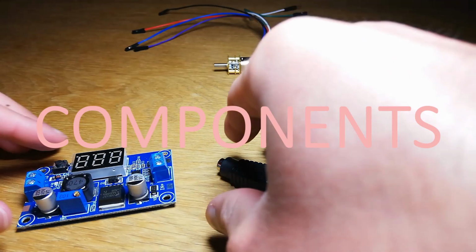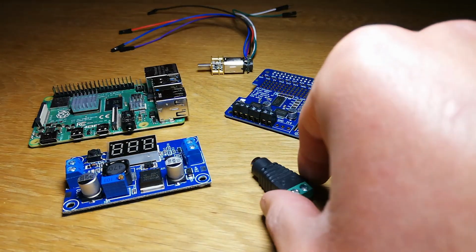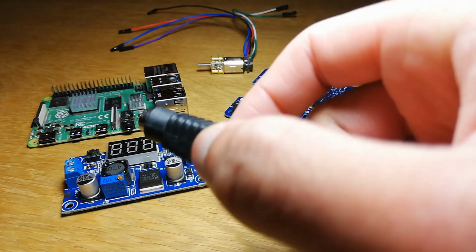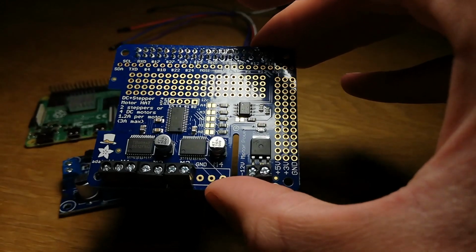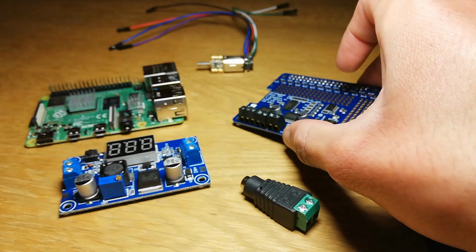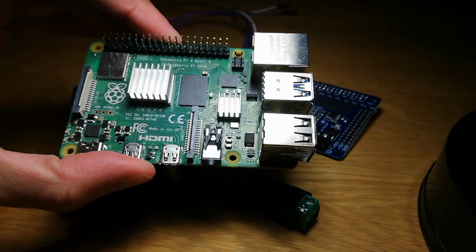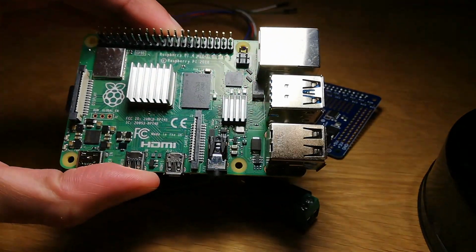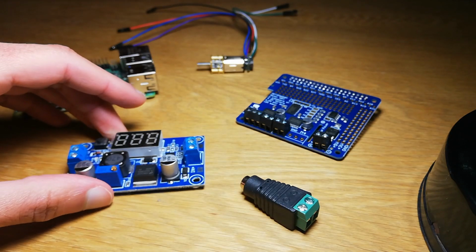For our power input, we're using a female DC jack barrel. This will be connected to a laptop charger. To control the motor, we're using Adafruit's motor controller hat. This generates the PWM signals needed to control the motor. For our computer, we're using a Raspberry Pi 4 Model B, which is running Ubuntu as well as ROS 2. And we'll also be using a buck converter to drop down the voltage of our laptop charger for our motor controller.